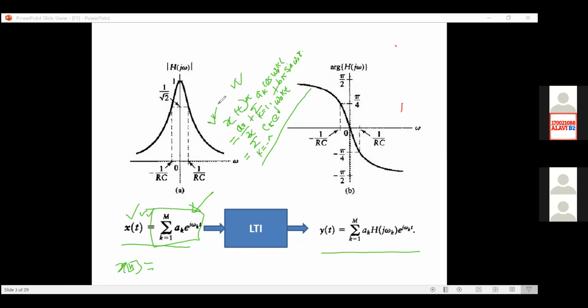And that tells us that in our trigonometric form, your ak, bk, and a0 are all real. But in your exponential form, your ck will not be real. Your ck will be complex. But this complex has a nature: it will appear as complex conjugates. The reason is that if we have a frequency omega and we are plotting our ck, then for a certain frequency, say k equal to 1, we have an amplitude there. At k equal to minus 1, we must have another amplitude there. Otherwise, these two cannot be added together to find your real signal. In this case, what will happen?